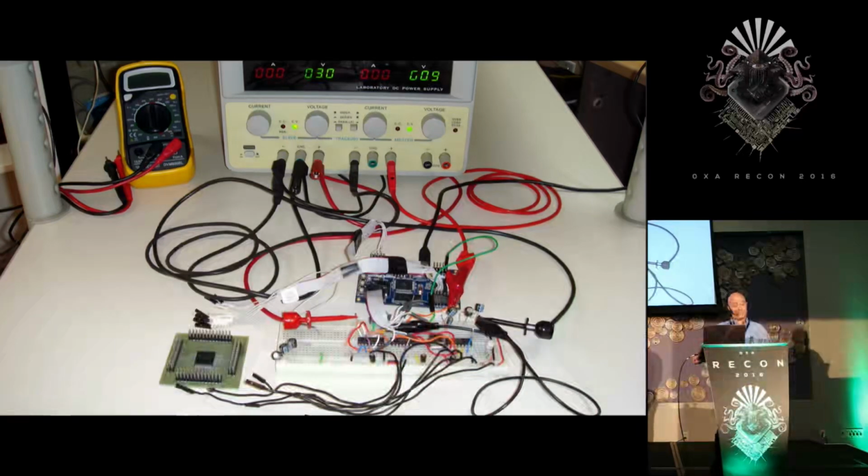So my glitcher design is pretty simple. It's based on the XMega board and a breadboard. I use the XMega to communicate with the ACP via SPI and to control the glitch. A 74 series 4053 analog switch is used to quickly switch the ACP VCC supply between 2 voltages, the normal level and the glitch level. I use a benchtop DC power supply with 2 outputs, so I can easily adjust both the normal level and the glitch level.